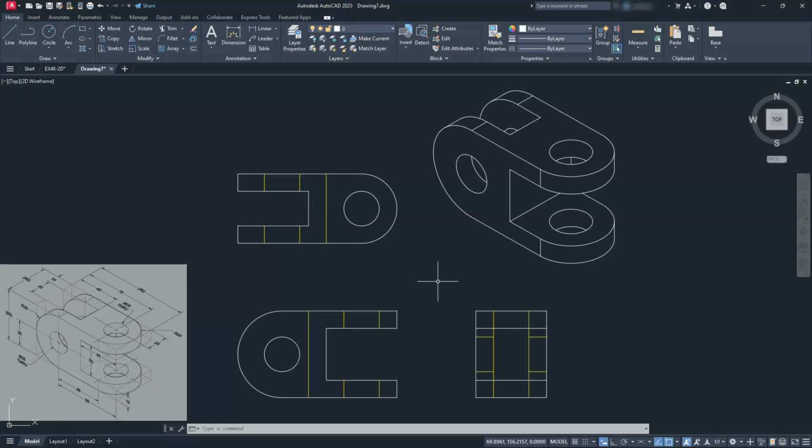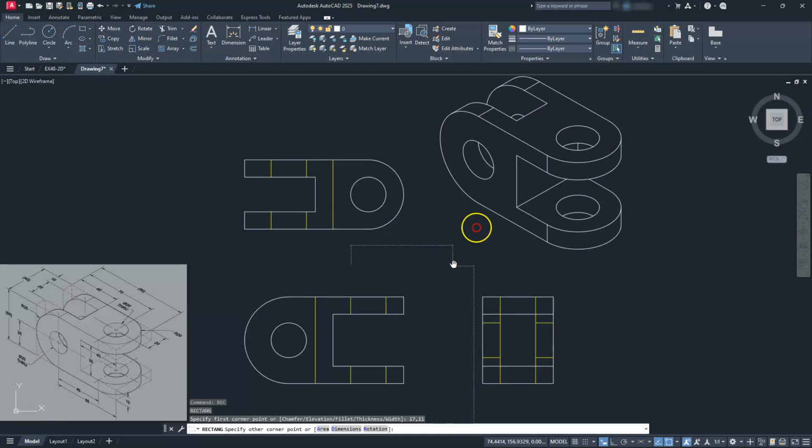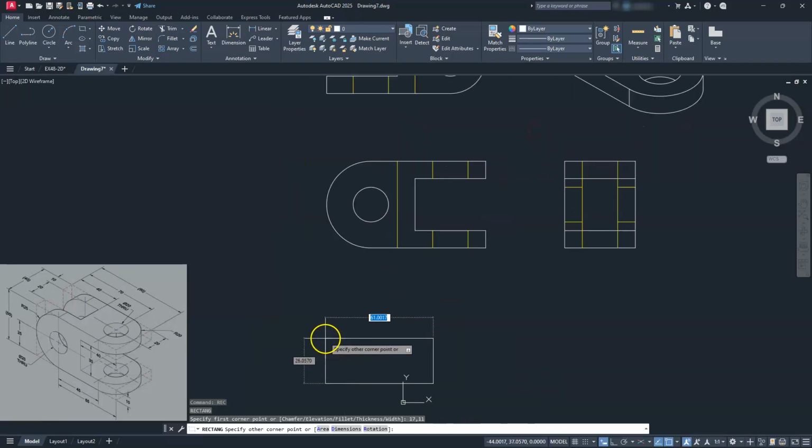So that being said, I'm going to start off by creating a rectangle. Let's decide what size paper we want to use on this, and I'm thinking a B size, so I'm going to type in 17,11. And the lower left corner should be at 0,0. I actually did that backwards.